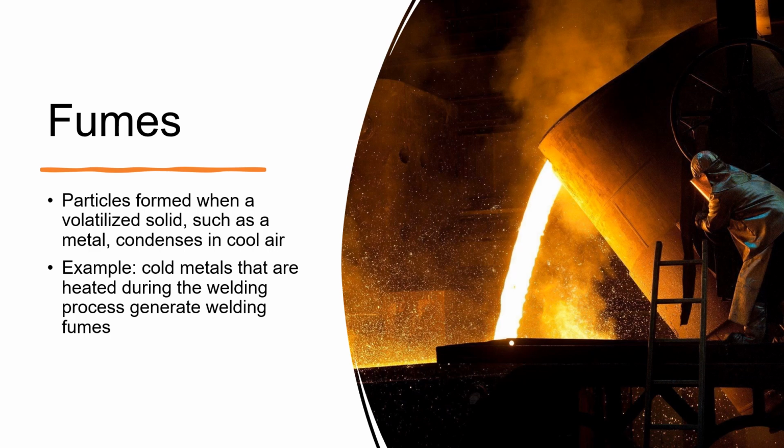So they have to wear special welding shields, and the heat is obviously part of that as well. But there are also dangerous fumes created as the metals are heated during this process. So not only do they need to protect their eyes and their skin, but they also need some respiratory or ventilation protection.